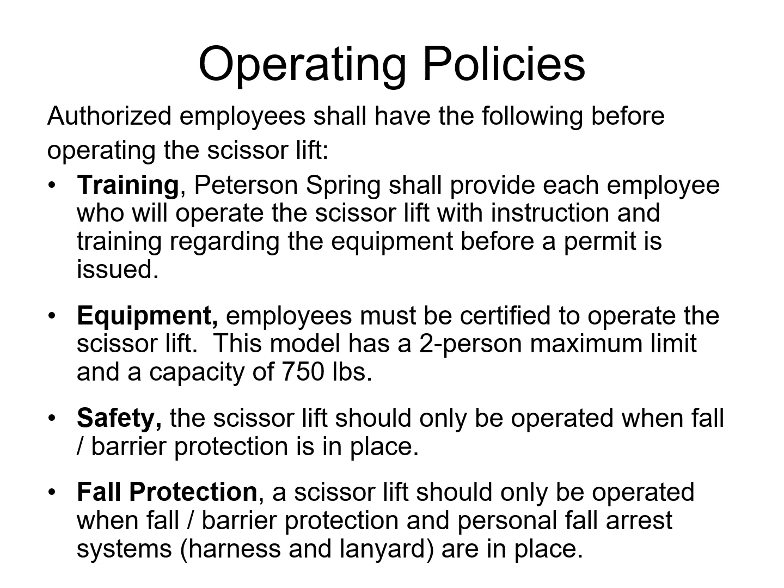Safety. The scissor lift should be only operated when fall/barrier protection is in place. Fall protection. A scissor lift should be only operated when fall/barrier protection and personal fall arrest systems, harness/lanyard, are in place based on company policy.